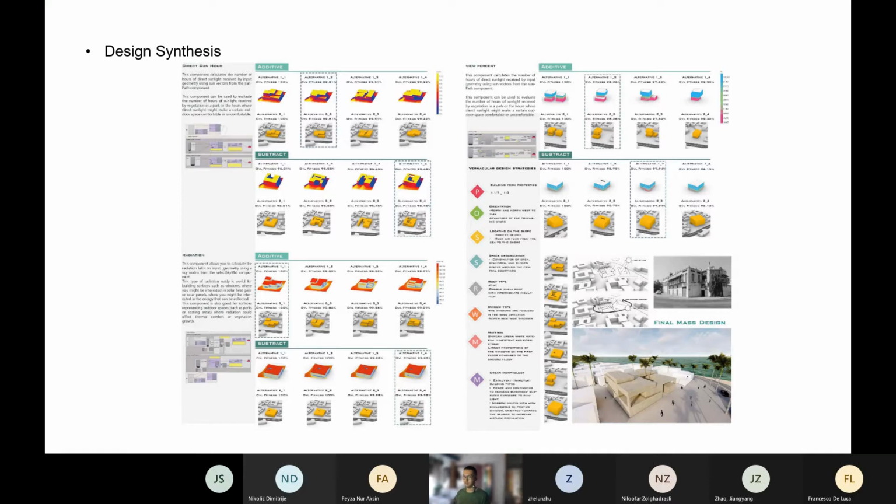They also found something interesting. If using the subtractive one, the result is quite similar to the vernacular building with the courtyard in the center or the very narrow alley, because this can create some kind of self-shading effect for the buildings. But when using the additive one, the results typically have a very large overhanging structure, and this overhanging structure also leads to the self-shading effect.